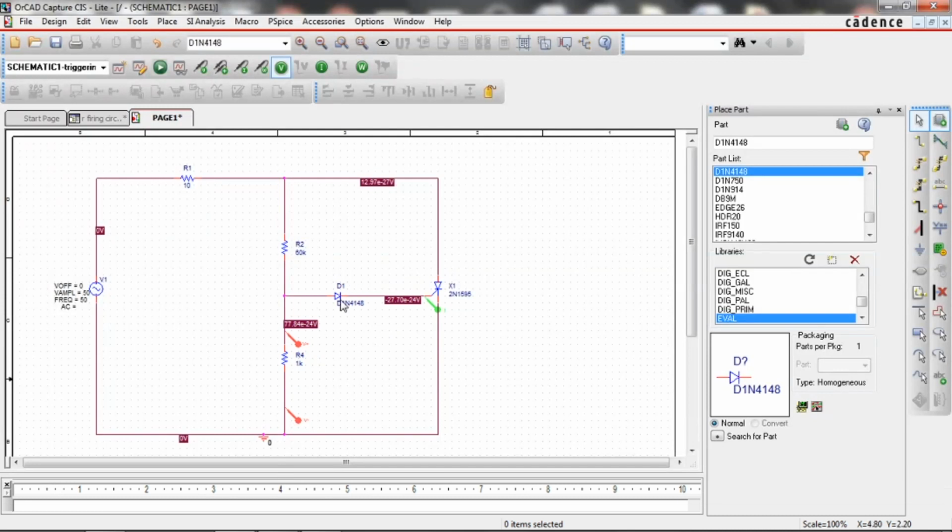See, we have used this diode to block the reverse current, but it is causing some problem. Why? Because while it is passing a forward current, there is a drop across the diode, that is 0.7. So from now onwards we should give some extra voltage from here, so that even after the 0.7 is dropped, the remaining is able to turn on the SCR. That's the reason I reduced this. I think you will understand. Okay, so this circuit is good.